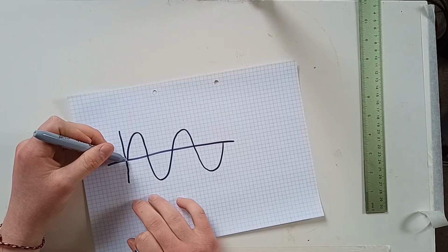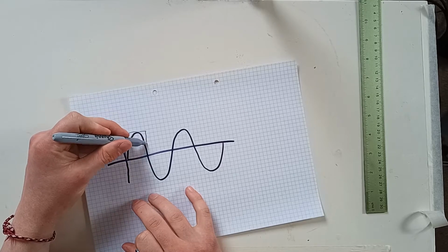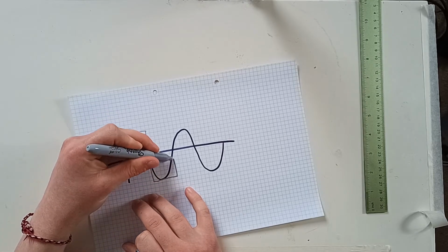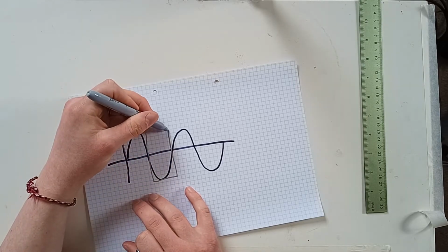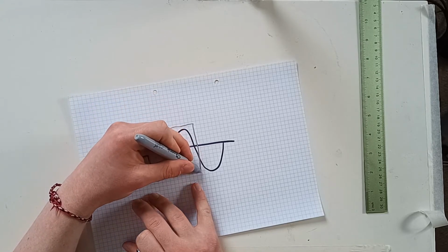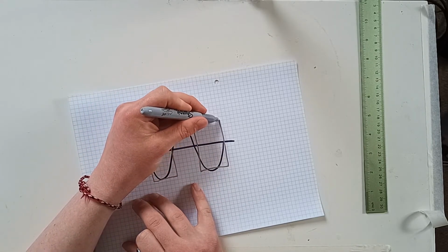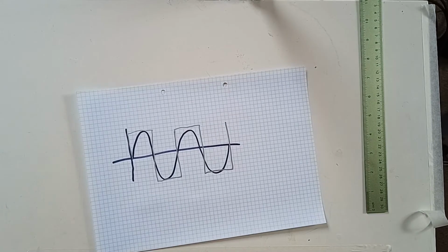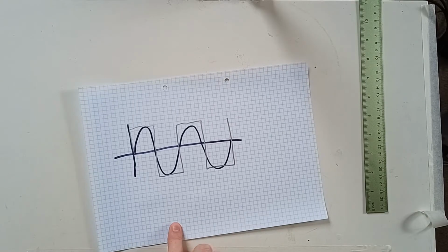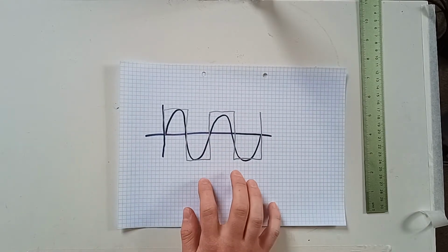The other most common would be a square wave, which has lots of different frequencies over the top of your base oscillation or sine wave. So if you were to filter everything off of a square wave, you'd be left with the underlying sine wave. This is a form of subtractive synthesis.